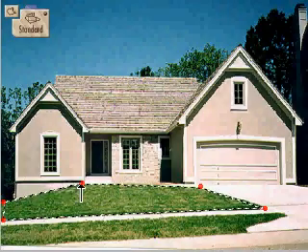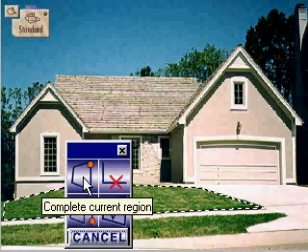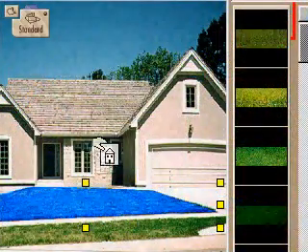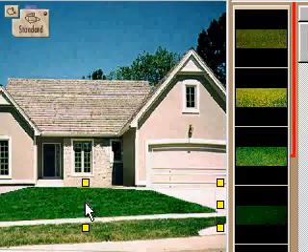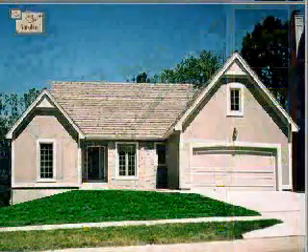When you are through, right-click, then select one of the options on the menu. In this case, left-click on Complete Region. Drag a pattern from the Image Library into the area you created. Note that the pattern fills the area. Substitute a different pattern by dragging it into the same area. When you exit this tutorial, the Freeform cursor is ready for you to begin.